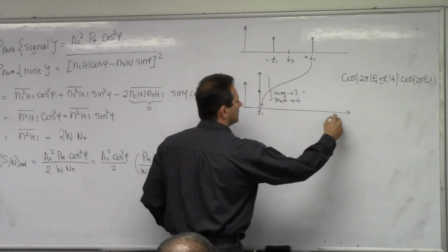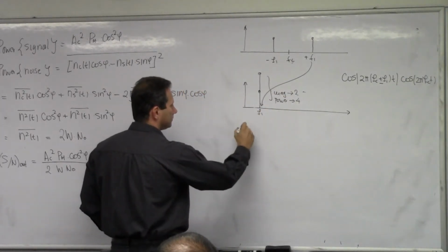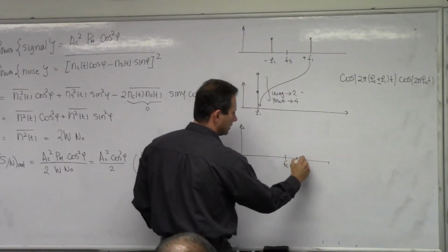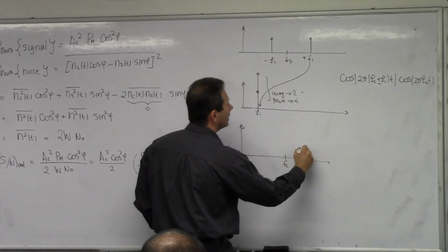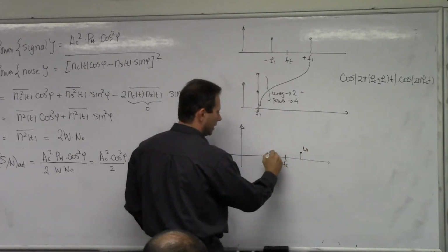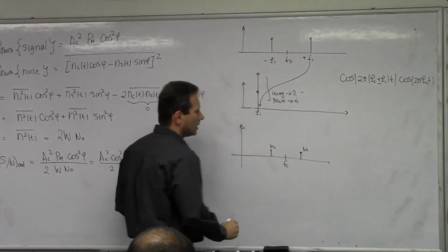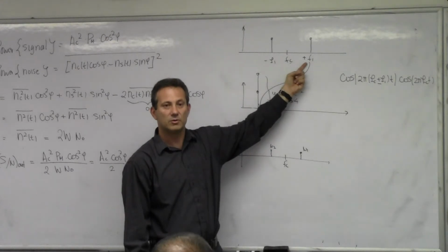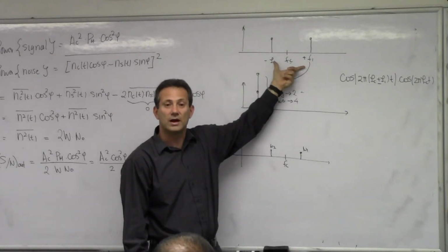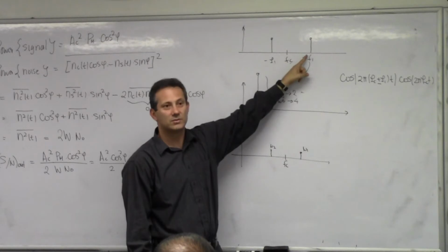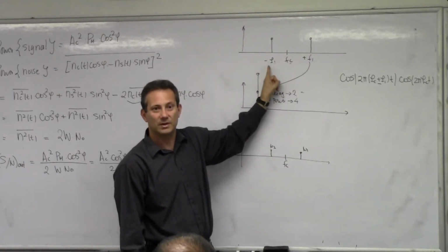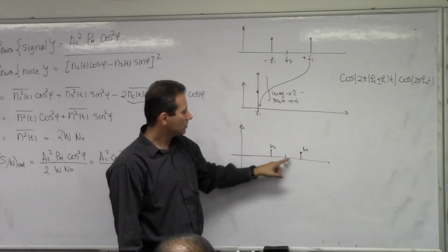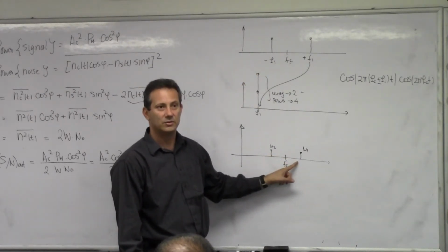Now, let's take a look at noise. Now you have Fc, there's a little noise component, let me call it N1, and a little noise component N2. The key thing here is that the origin of these 2 is the modulation, so these 2 are in phase. Whatever is the phase of this one, it's the same phase as this one. So when you bring them down, they will add in amplitude. These 2 noise components have a random phase relative to each other.